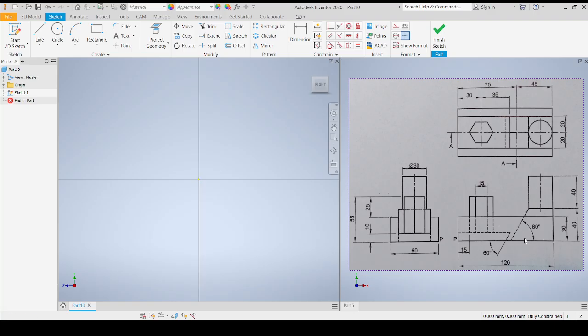Okay? So now we're going to start by analyzing our sketch. If we come here and analyze our sketch, you can see that there's an extrusion of a hexagon. It's still within there. And then there's a wall, right? And this wall, the length of 30, is this wall if you look at it in the top view. So we're going to start off by designing the elements that are on the inside. We're going to start off with this one, the hidden line element.